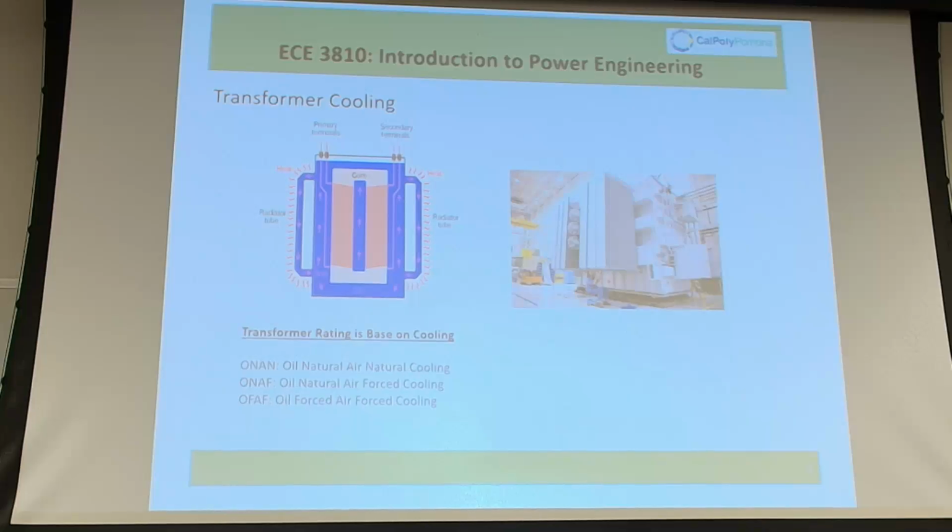It's not so much the conductivity, it's that you can heat the oil so much that you destroy its properties. Then you can have other problems, a lot of other problems, and then you get damage. So keeping the transformer at a normal temperature is key. Every time you heat up the transformer beyond its normal operating or rated temperature, you're eating up its life. Does this oil usually get drained out and replaced?